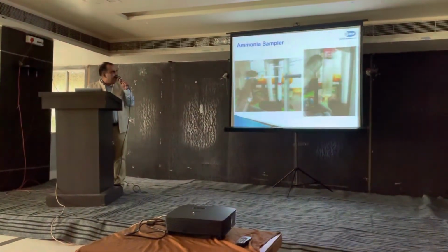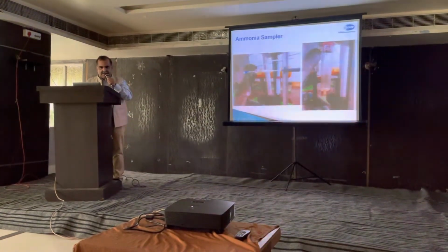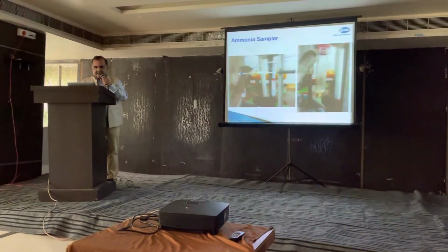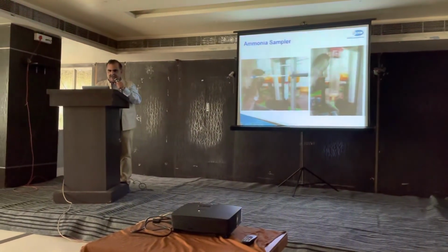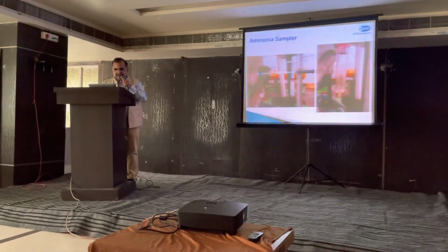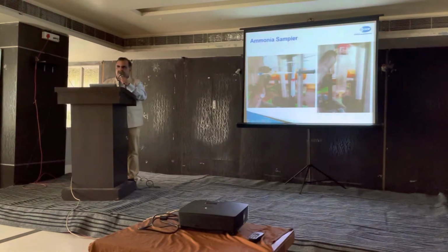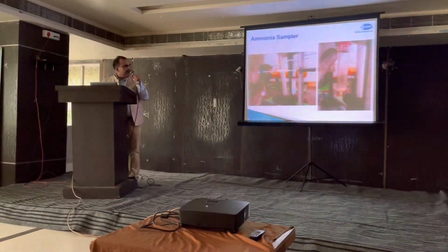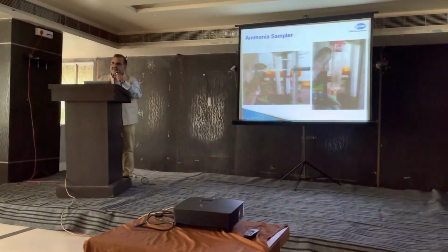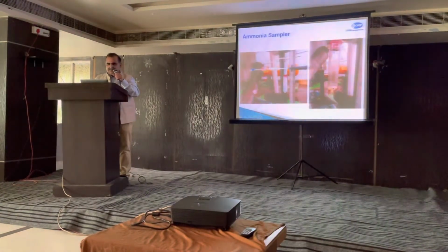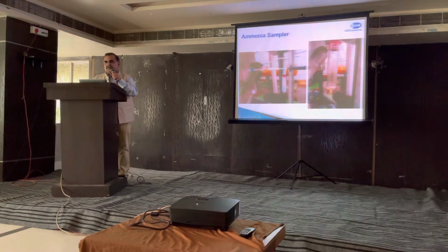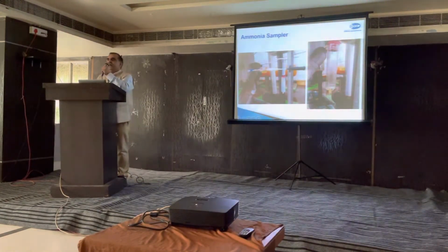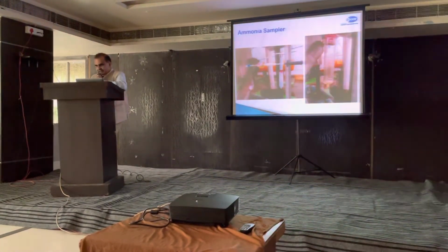So if you see, this is the actual system connected from a pump header. It was filled with ammonia, and then slowly the ammonia evaporated, and you can see here around 6% of water being found in the system. So this tells us that you have 6 or 7% of water in the system. So it totally affects your system, you will understand how much it affects.